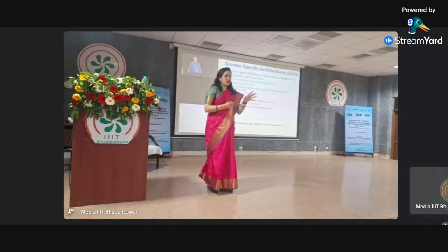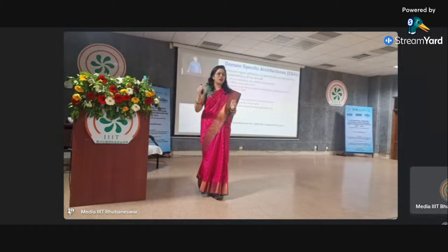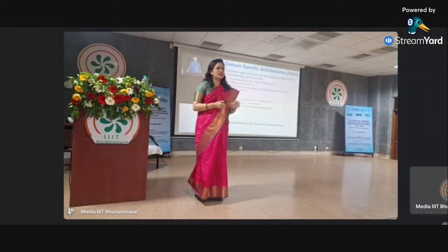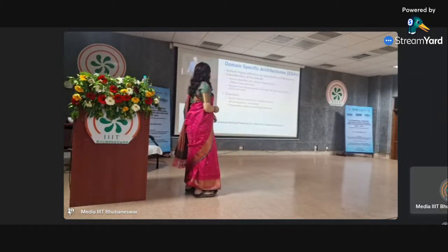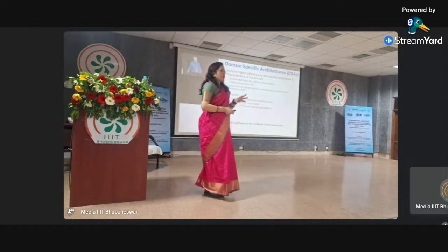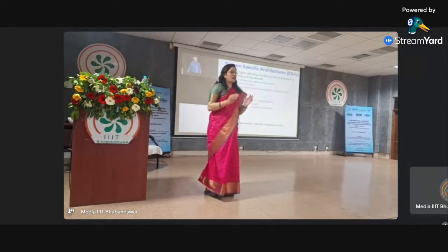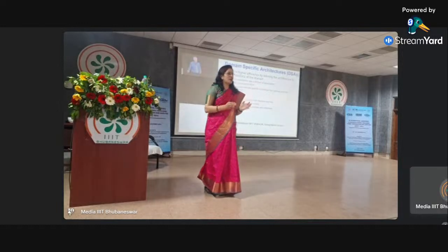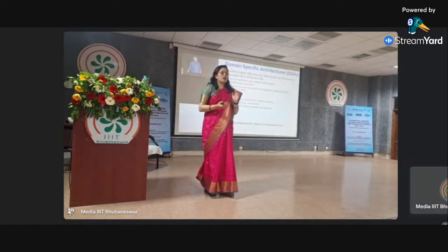Object detection is just mathematical addition and multiplication. We can have more adder and multiply units, and remove the units that do square root and trigonometric operations. That is exactly what special-purpose or domain-specific architecture design is. By this, we make sure we have dedicated cores which are good at the functionalities that we need, and they also consume comparatively less power.